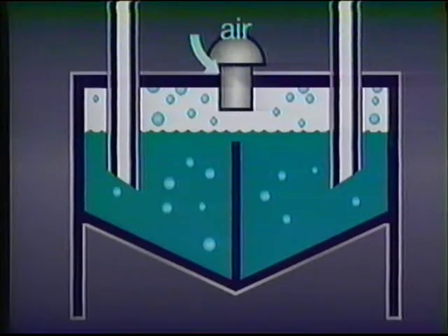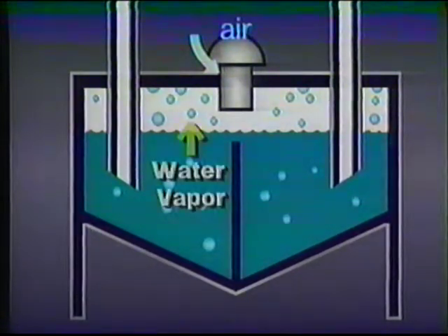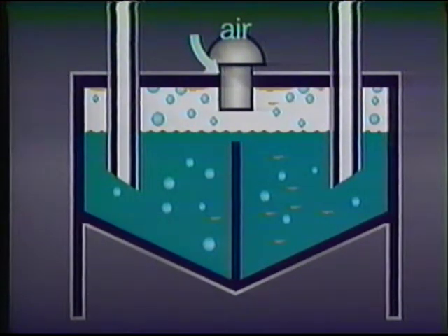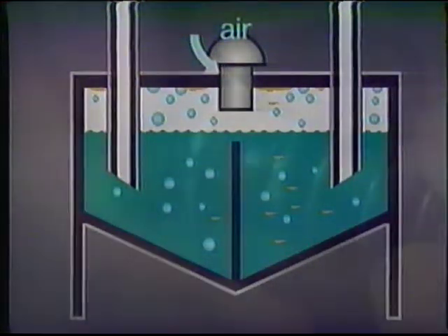Air entering the system during operation can also cause serious problems. Air contains water vapor, and when the fluid is allowed to cool, the water condenses on metal surfaces. This can lead to rust, which eventually ends up in the fluid. The rust particles can clog orifices, interfere with lubrication, cause unreliable operation, and create maintenance problems.